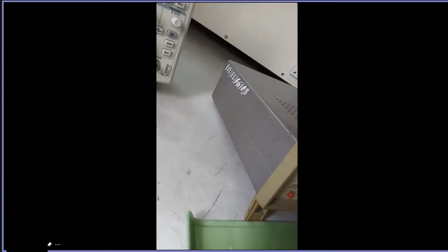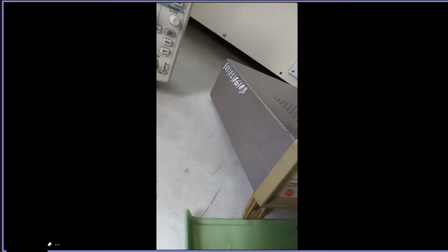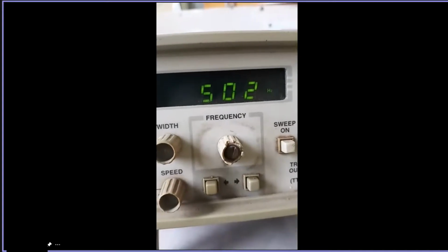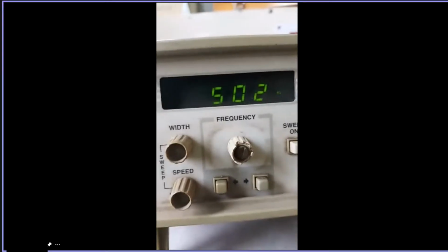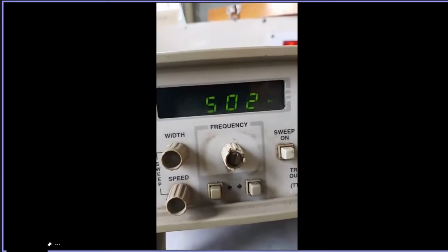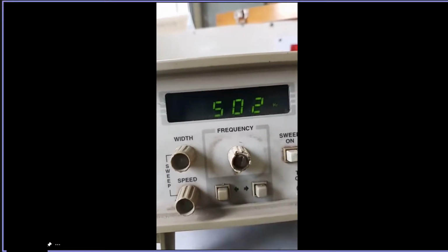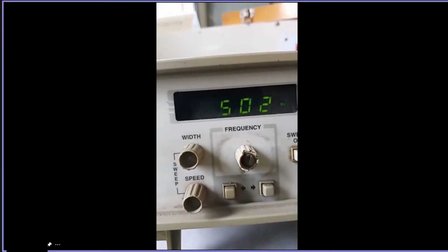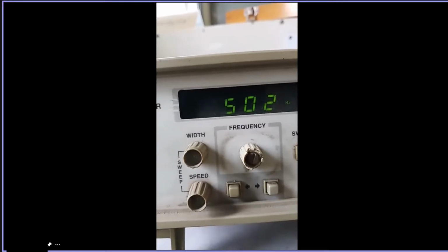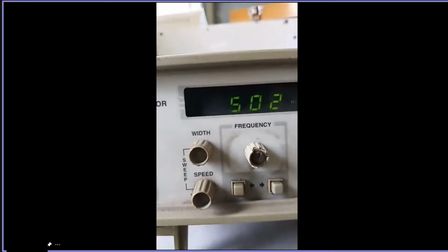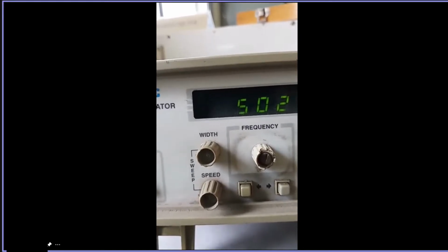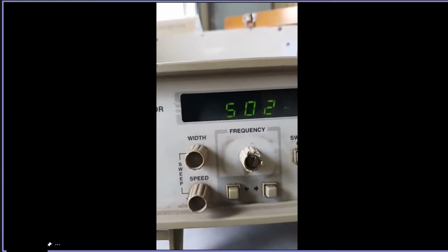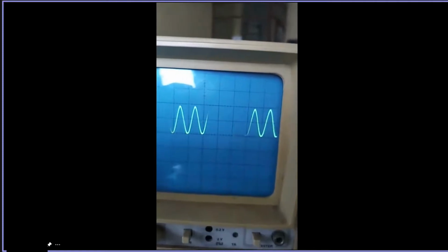Okay, so now we are going to check it. It is a filter, right? So for a filter the most important criterion is the frequency, so that's why we are changing the frequency. The magnitude is not going to change, it is still the same, so the input signal only we are changing, right? So we can see that it has allowed 100 hertz, it has allowed 300 hertz, now it is allowing 500 hertz also, right? And the same voltage. So you can see the output of the second order.